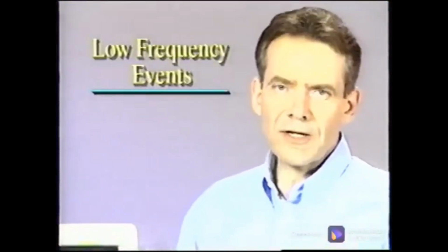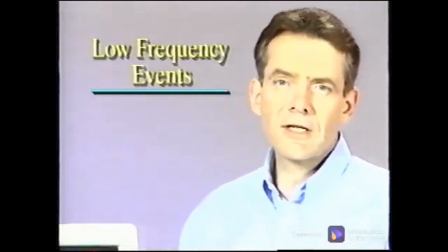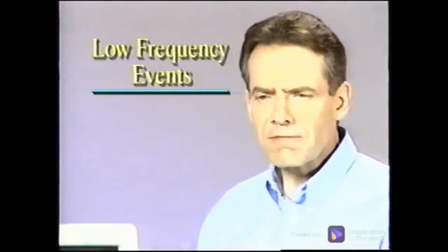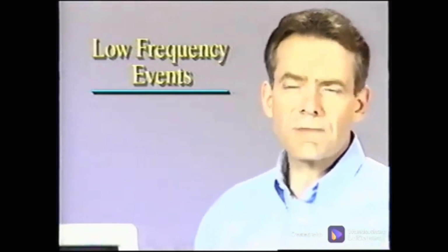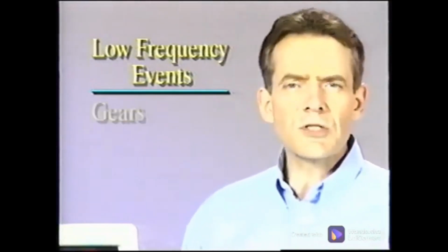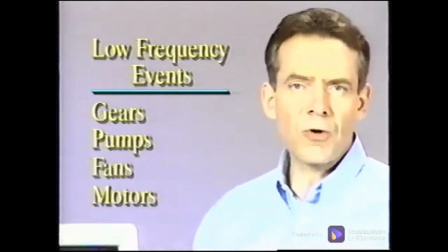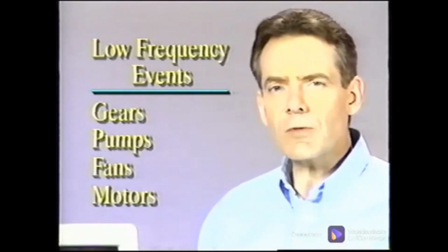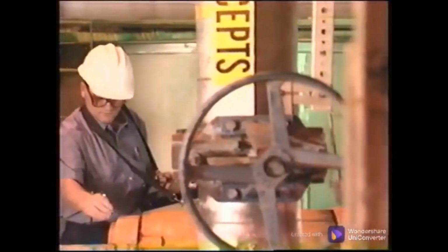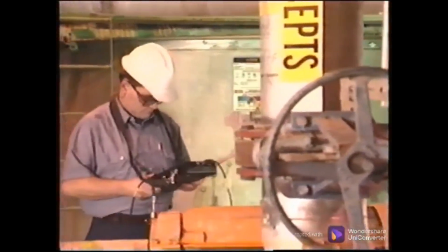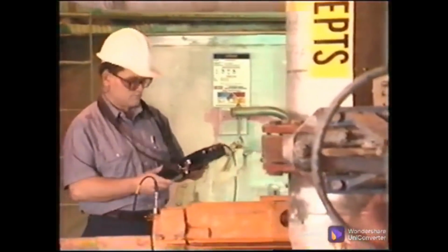Events that occur a few seconds apart are missed by many analysts, and problems that stem from these events can take an analyst by surprise. These events can occur in speed reduction gearboxes or may occur in typical pumps, fans, and motors due to process variables or transient events. Normal routine data collection on typical equipment may not capture low-frequency or transient events.